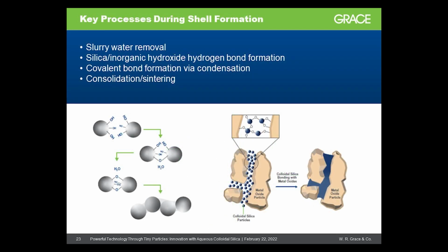There are several physical and chemical processes that are involved with shell formation. First, the shell must be drained of excess slurry and then partially dried. This occurs via evaporation of liquid at the shell surface after a capillary network has formed between the refractory and binder particles. This capillary network is formed when the liquid phase transforms to an elastic gel state via hydrogen bonds between the hydrous oxide surfaces. The formation of the gel state depends on both the concentration of the colloidal silica as well